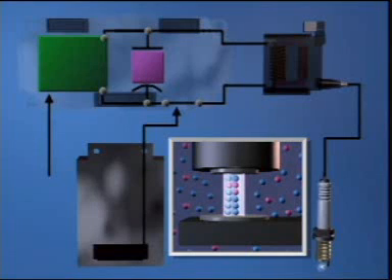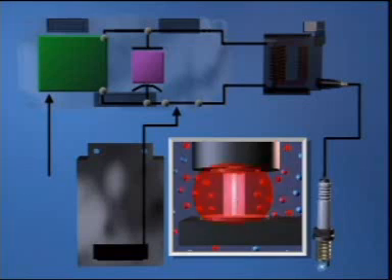The plug continues to arc until the energy in the secondary winding is dissipated below the breakdown voltage, or until the switch is opened, removing the capacitor from the circuit. This allows the capacitor to charge for the next cycle.